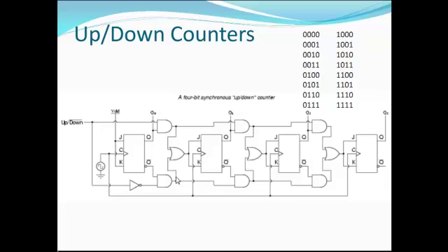So all of these AND gates are outputting 0, and these OR gates then are ORing zeros and outputs from the up counter, so up counting has not changed at all.